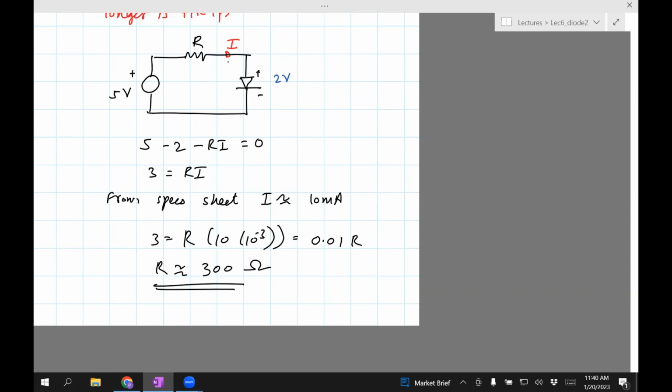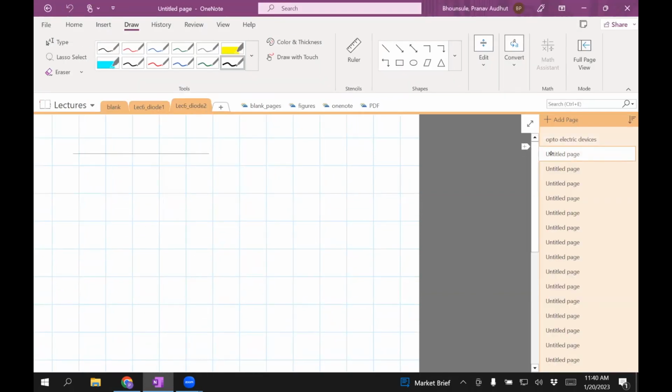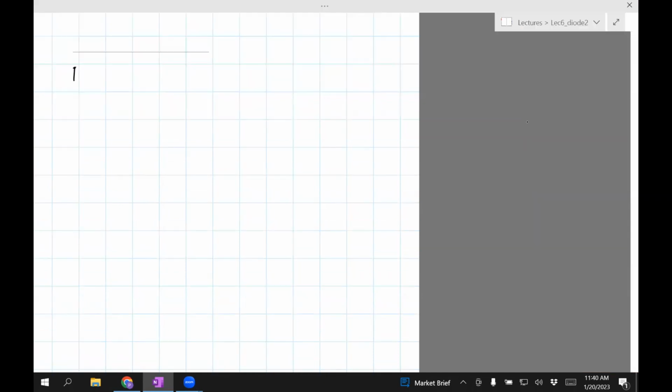Okay. So this is a light-emitting diode. We have what is known as a photodiode. Photodiode, unlike an LED which emits light, becomes conducting the moment light falls on it, and so it can be used as a sensor. Okay, so the way a photodiode is connected is as follows. So here we are connecting it in reverse bias. And then of course you want to put a resistor.